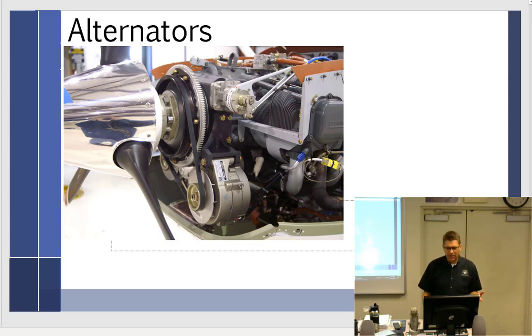One of the tests that I do all the time, every annual, is put your fingers in there and see how far that fan assembly moves without moving the propeller. You're not going to move the prop with your finger touching the fan assembly because it's small, plastic and gear driven, but it shouldn't move a whole lot. There's going to be some movement, but especially on the smaller Continentals, like on the 150s, they can get to moving a lot. And when they move a lot, it means that the drive bushings inside the engine, which are made of rubber, are going.